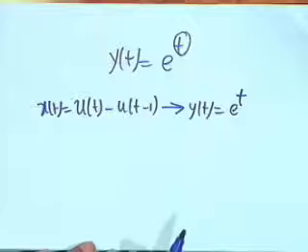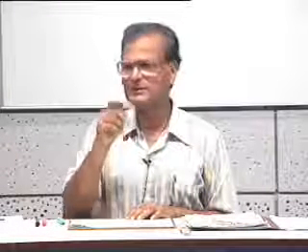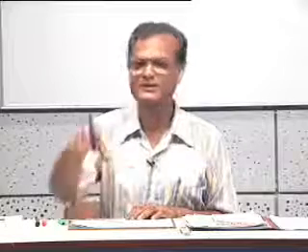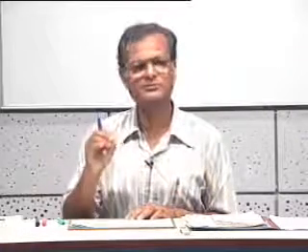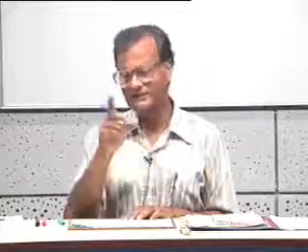Obviously unstable. If under one condition the system output grows indefinitely, that's enough to characterize the system as unstable. Is that clear? On the other hand, you may test under 100 or 1000 input conditions, and each of them leads to a bounded output. You cannot say conclusively whether the system is stable or unstable. Is this clear? Again, the same analogy.